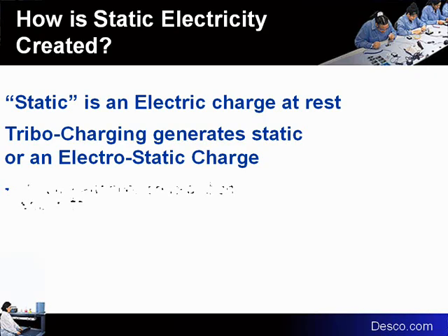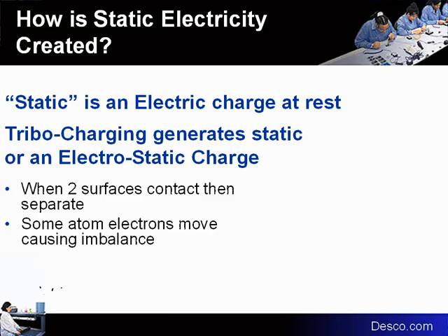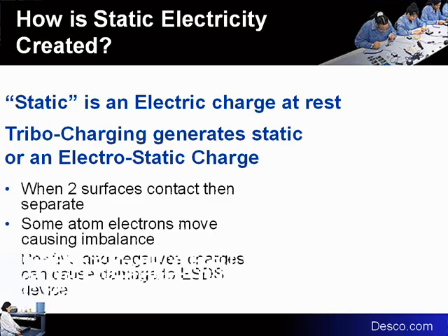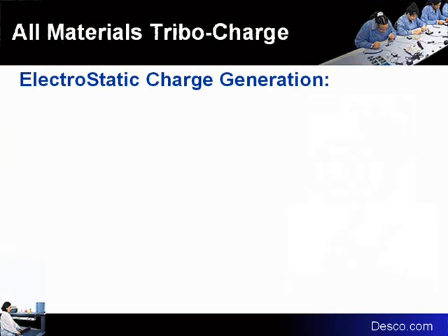Some of the basics. Static is an electric charge at rest. Triboelectric charging generates static electricity. So anytime two surfaces contact and separate, electrons transfer from one surface, causing an imbalance. Positive and negative charges both can cause ESD damage.